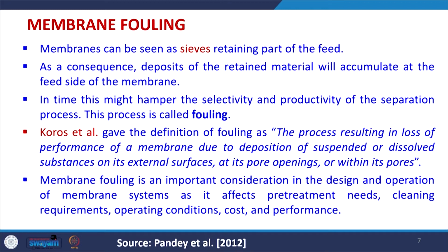So, they are like a filtration unit, and because of this a lot of deposition happens on the membrane surface. The deposition of the retained material always goes on accumulating at the feed side of the membrane itself, and this cake deposition starts accumulating and may become very high.